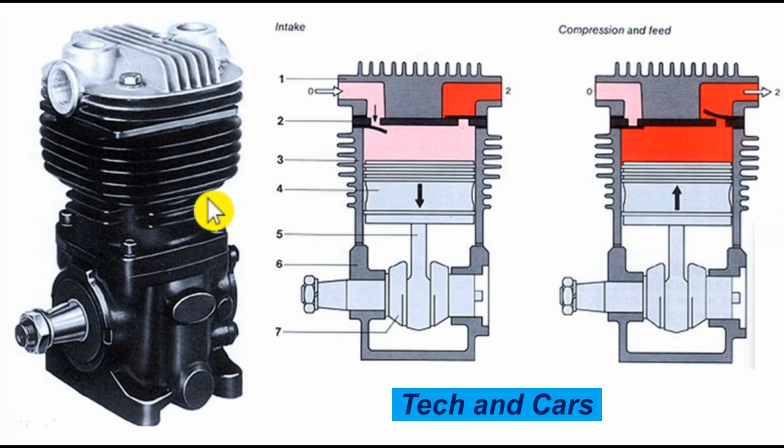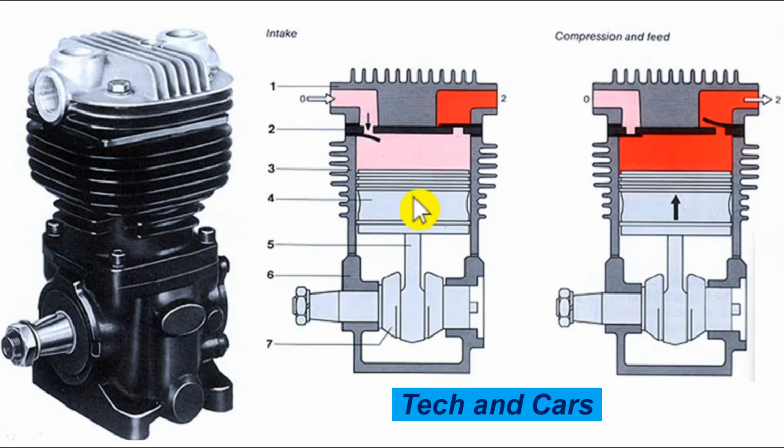On some air compressors, instead of using a single piston, some massive air compressors use double pistons as well. Lubrication must be there, so always ensure it is well lubricated. The lubrication system is usually connected to the engine lubrication circuit so that oil will be fed to the crankshaft bearing, and the cylinder walls are also partially lubricated by engine oil splash. So this is how the air compressor inside the air brake operates.